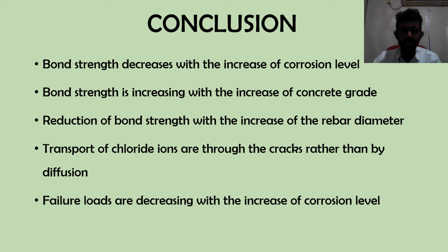The chloride ion concentrations are increasing in depths from rebar towards the outer surface, and hence the transportation of chloride ions is through the cracks rather than by diffusion.